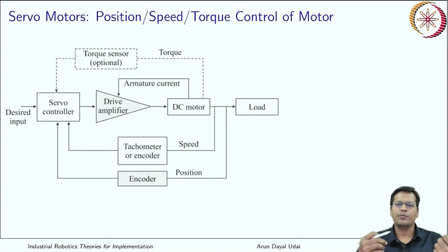Okay, so that will give you a feedback where I am, where the motor is, and then you can have a sort of controller which can exactly compare with the desired angle where you want, and you can stop it. So this is a type of servo which I am talking about. So this is a general layout of standard servo motor. In this figure I have shown DC motor. It can also be AC motor. It can also be a BLDC motor.